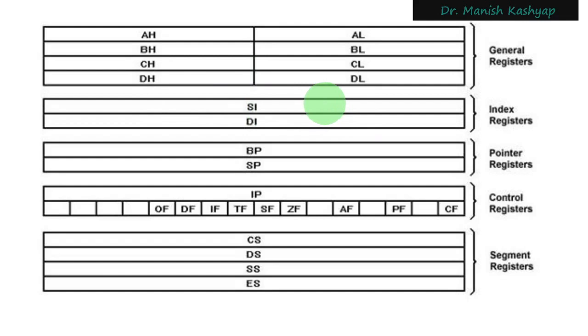To be able to address every location inside the 64 kilobytes, you only need 16-bit addresses. That is why the index register contains the offset. It contains the index of locations within that 64 kilobyte segment. So SI will contain 0004, DS will contain 5000.